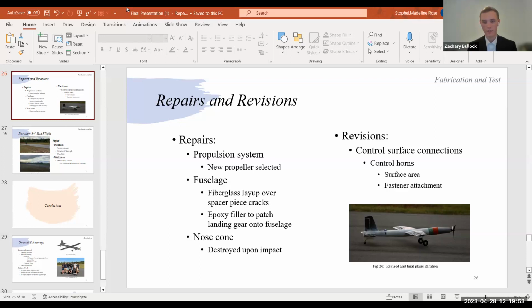If we were to address something like that, I would like to do a prolonged test with the motor spinning, perhaps with the plane mounted in a static location, to give it a spin up and see how the ESC responds to prolonged high motor speeds, and determine whether the temperature would fall within a safe range. And if it does, then perhaps allow for cutouts in the nose where the ESC was located to get airflow over it to help cool it.